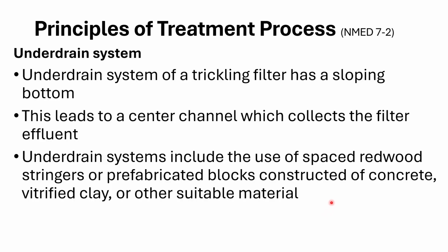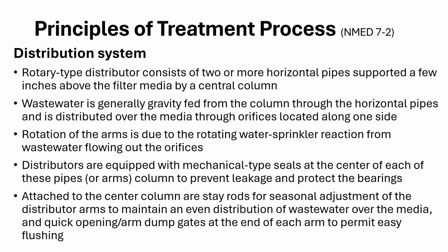The underdrain system can be redwood stringers or prefabricated blocks made out of concrete, vitrified clay. I've seen pumice in some cases or other suitable material. But the idea is it's going to allow that filtrate to come down, collect, and flow towards the outlet.